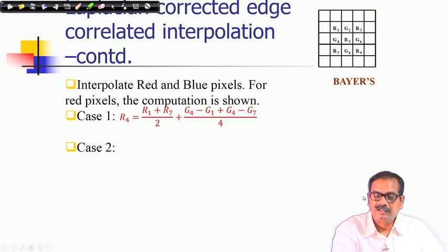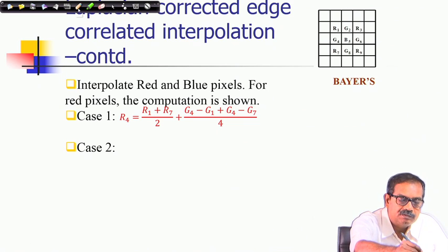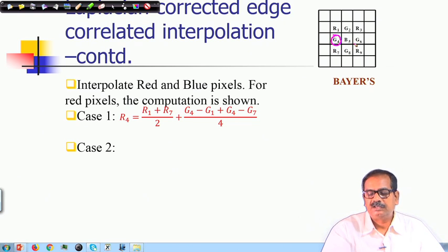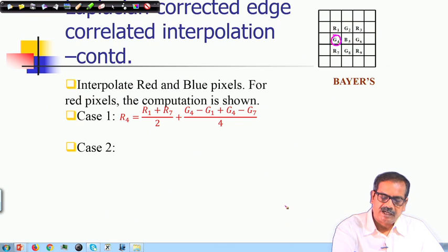If it is at this location, you can see this is the location where the missing red is computed, and only the vertical neighbors are available for red samples. So, there is no question of comparing horizontal and vertical gradients in this case, because information is available in only one direction, and that is more reliable than the other values. We will use them while doing interpolation, and also refine this estimate using the cross channel Laplacian estimate as we mentioned.